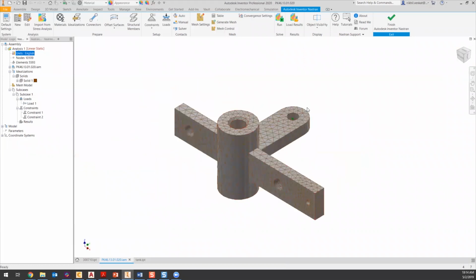Okay. Now the new feature is the mesh convergence portion of it. To back up, we've talked about mesh convergence in one of the previous AVAs from last year, I believe. The mesh convergence setting in general is a metric to determine how accurate your solution is with respect to your mesh.